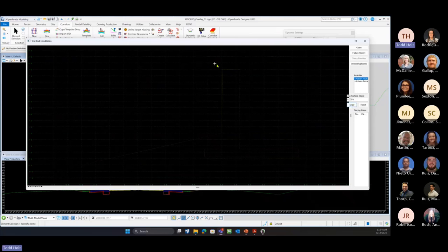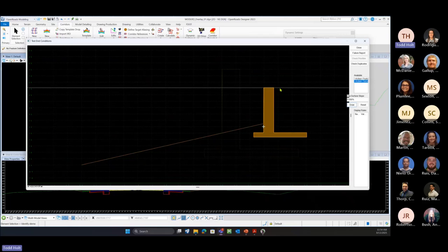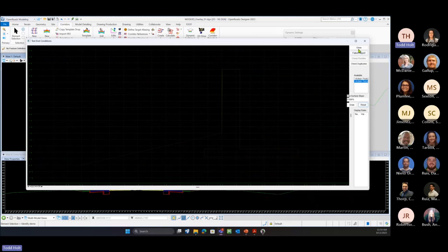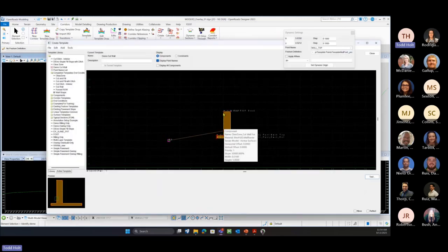So there maybe our wall existing is out to this point. And then if I draw my terrain, our wall is going to draw, and now it's going to start drawing the wall up to the existing ground to that certain height. So I'm building in a display rule or a component relationship so that the wall component is only going to draw if the existing terrain, that end condition, is met. So the different conditions that we're building into this are met.